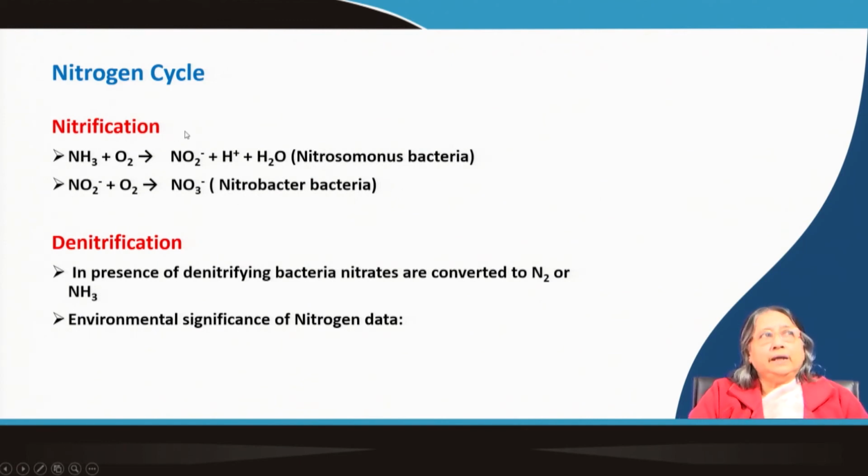You have seen in the BOD determination, we always do the 5-day BOD. But why do we do the 5-day BOD? Why not 7-day BOD? Why not 10-day BOD? Because after 5 days, this type of nitrifying bacteria oxidize the nitrogenous compounds like ammonia.